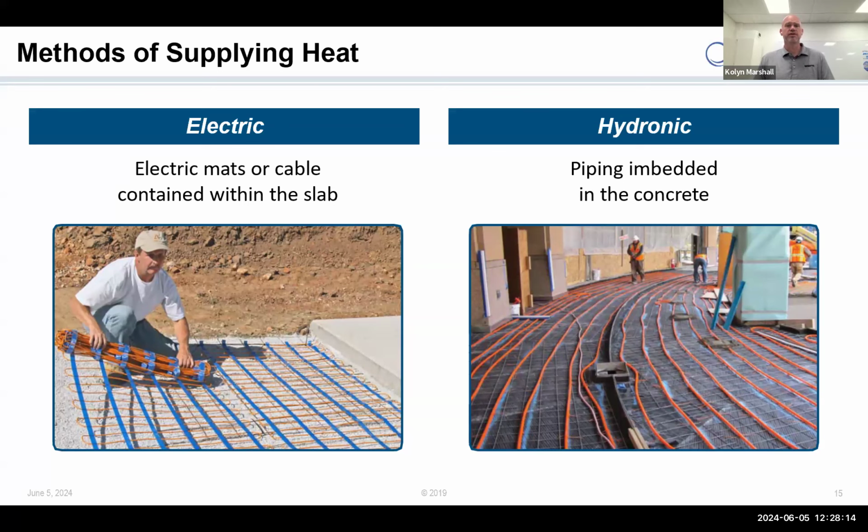Electrical systems really excel in cost savings on small areas. Usually the trade-off is around 1,500 to 3,000 square feet. That's going to be the gray area between whether or not it's more advantageous for one or the other. Under 3,000 square feet, it's going to be electric. Above that, it's going to be hydronic typically. 1,500 to 3,000 is kind of gray. They kind of overlap as cost goes and system needs are. But that's kind of the breakout that I've seen.